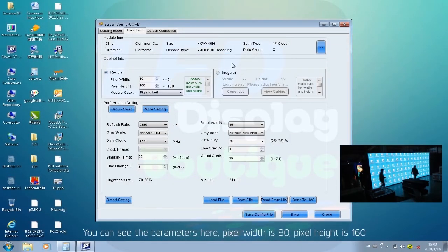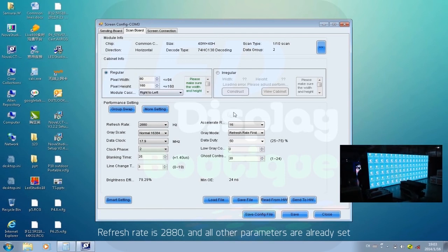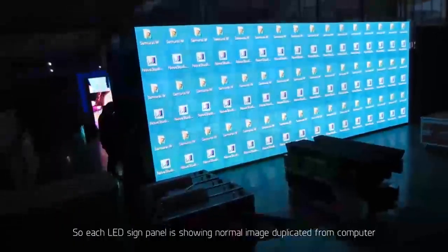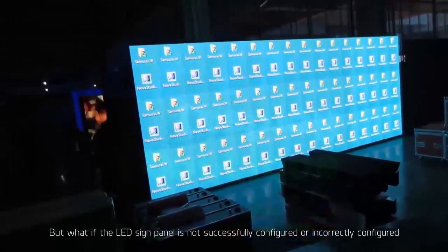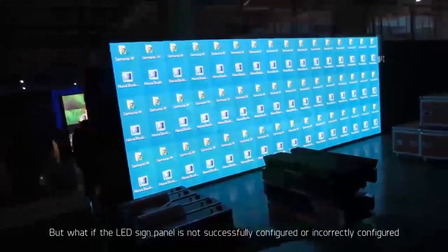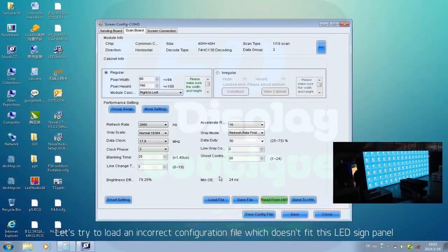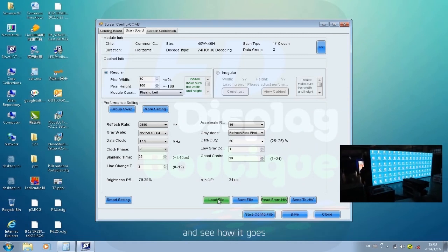You can see the parameters here. Pixel width is 80, pixel height is 160, refresh rate is 2880, and all other parameters are already set. So each LED sign panel is showing a normal image duplicated from the computer. But what if the LED sign panel is not successfully configured or incorrectly configured? Let's try to load an incorrect configuration file which doesn't fit this LED sign panel and see how it goes.